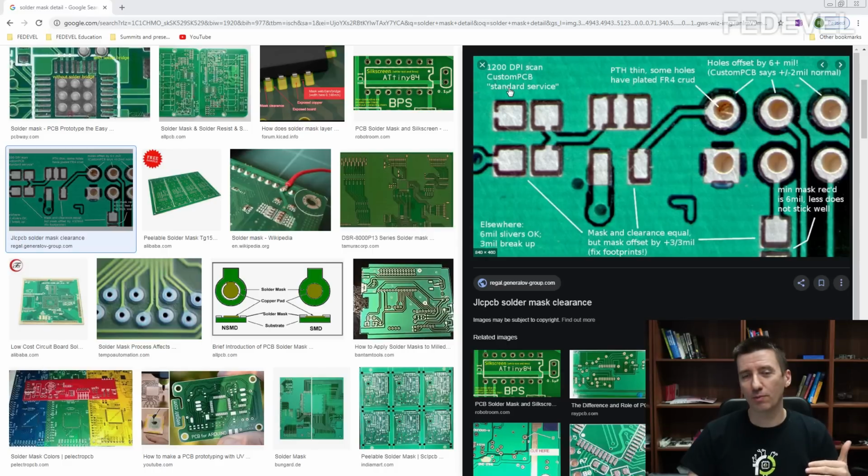But you need to be very careful, because some PCB manufacturers may not be able to actually create so small a gap between the part and the mask opening, because they don't have such precise machines, so they will make the opening bigger anyway. But there are other reasons why you would like to see this mask opening during your design process when you are creating the board, and one of the reasons is mentioned in the next clip. So let's have a look.